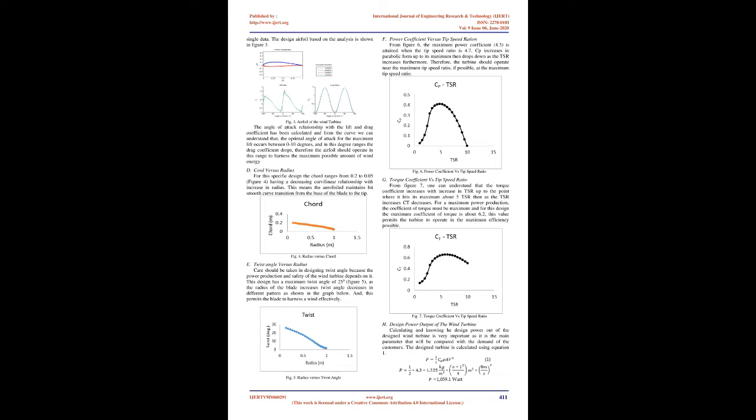This corresponds with the case when the shell is at the maximum thickness, thus creating a solid blade. If the structural data panel is set to hollow, the shell thickness represents the thickness required to maintain structural integrity of the blade. Fig. 2.